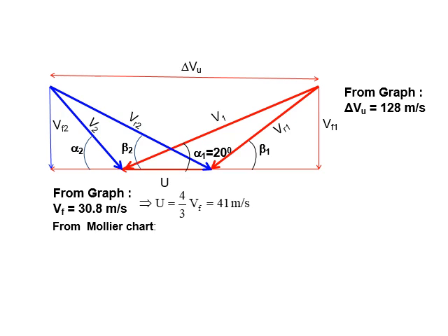From the Mollier chart, since the pressure is given as 2.7 bar for dry saturated steam, with dryness fraction x equals 1, the density is calculated as 1 by specific volume, where v represents specific volume. The density value is 1.5 kg per meter cube.